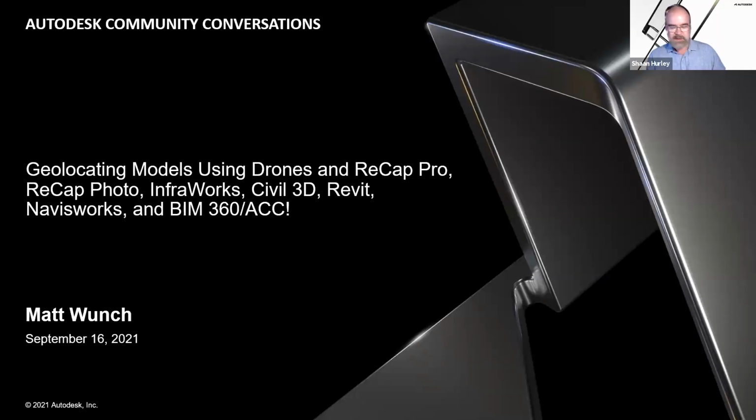Now we move further down. We want to specify an area of interest to pull in. So I'm going to select an area, because I rarely ever want to pull in the entire extent of the model. If you don't have maps already set to show, you'll get a little pop-up that says, do you want to use maps so you can actually see where you're selecting? You can just say yes and not show this again, and it'll automatically display the maps every time. All right, so this is the area that I want to pull in. I'm just going to do a little rectangle like this. Wait for this to churn up as it reads the model.